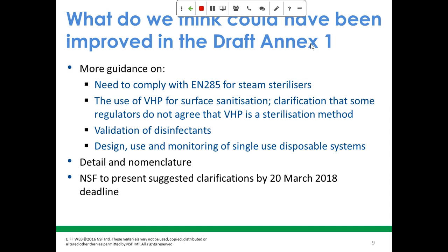We also felt that there should be some more information about the validation of disinfectants, specifically how to validate them, how to perform ongoing monitoring of them, what types of flora, standard flora and also cleanroom flora would be chosen, and what kinds of specifications for the validation would be expected.